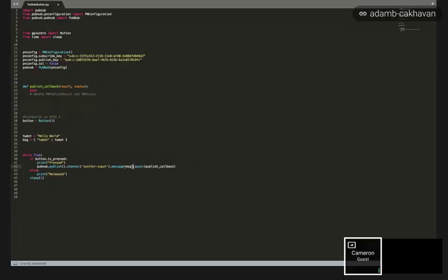And then if you want, you can make an asynchronous callback to whatever function we talked about earlier, but we didn't do that, so it's okay. And I add a little delay here, because if you add a delay here, it'll just make sure that the program's not running too fast for our liking. But that is pretty much the simple way you would code most IoT things. The only things that would differ would be obviously your GPIO initializations and then what you do with whatever library you choose to use. But this is exactly how you do it for a push button and for many other simple cases like this. Awesome.